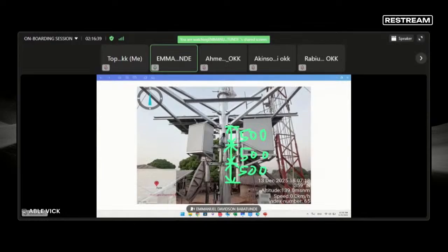The power cabinet is a three-way bracket, and the three-way bracket should be installed from the solar flange that is connecting to the solar structure from the tower. Measure 500 mm down. At that point, that's where the first bracket should be installed. From the first bracket, measure another 500 mm down. At that point is where the second bracket should be installed. Then you can install your pole, then mount your cabinet on it.